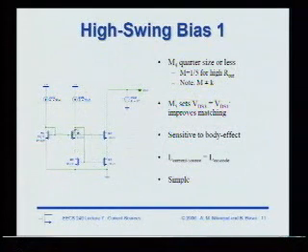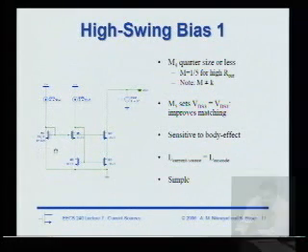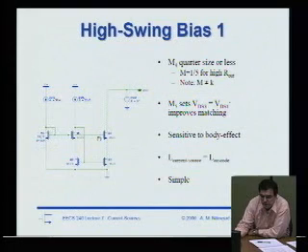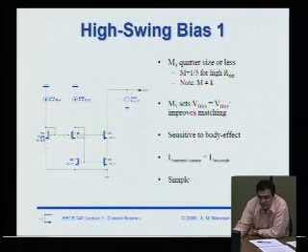Okay? And for the moment, let's forget about this transistor. Let's just ignore it. To get the VG value for M2, all I'm going to do is scale a device, run some current through it, and because this is a scaled device, I'm going to get roughly the right VT plus overdrive voltage here. So for instance, if I want 1 VT plus 2 overdrive, I just make this a quarter size device. That's the same trick we just played. So this device biases up this transistor, and this transistor here is our reference path.